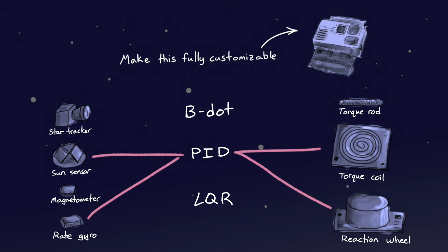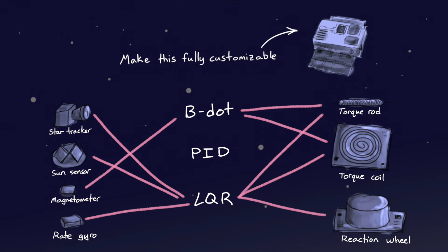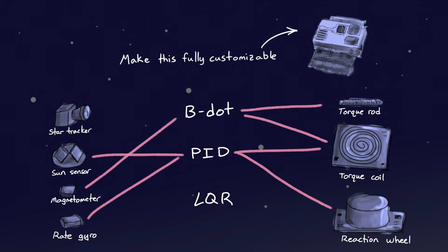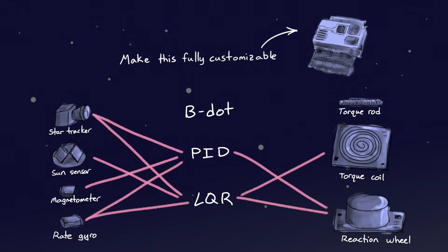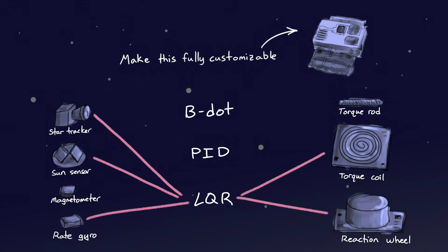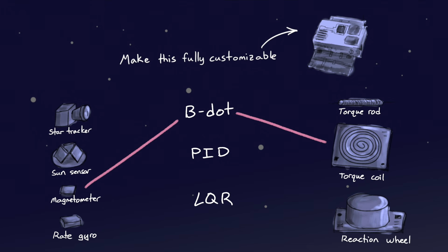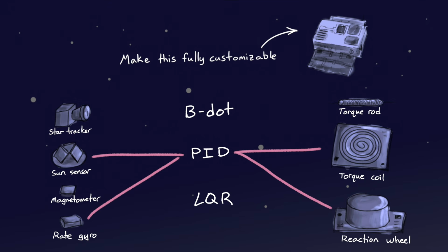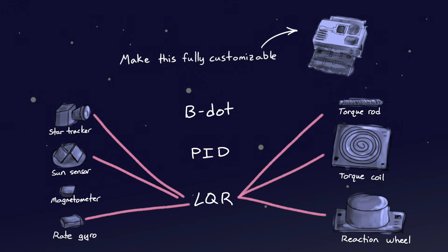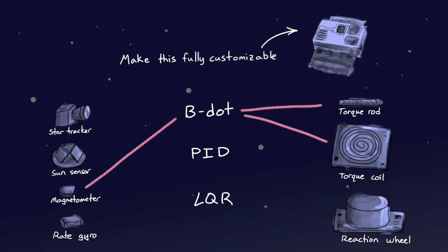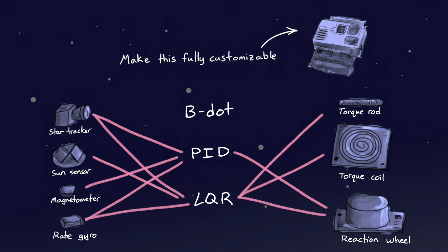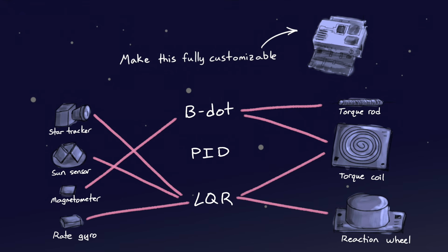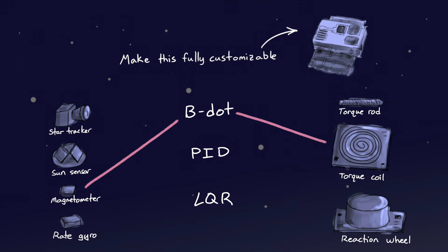And I thought I was being kind of clever in allowing it to be this flexible. But during a design review, someone pointed out a problem. By adding in all of this flexibility, I had created a system with effectively hundreds of states and state transitions. And that meant that it was going to be nearly impossible to verify every scenario, nearly impossible to achieve full coverage, and ultimately impossible to guarantee correct behavior on orbit. So instead of increasing confidence by allowing the system to be flexible, I had actually reduced it because I created a system that could easily hide failures, and I'd have no way of knowing.